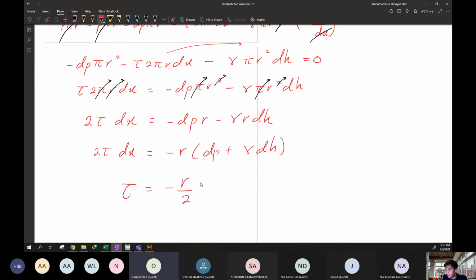Okay, this d we can factorize as well, d over dx. This is dx from here, and pressure plus gamma h. Okay, you can see the differential for pressure is valid. The differential for gamma or differential for h? Anyone? Which one is correct? D gamma or dh? DH. Okay, why h? Why not gamma? Because h will vary. Height will vary. Okay, yes, perfect. The h will vary, but the gamma is constant.